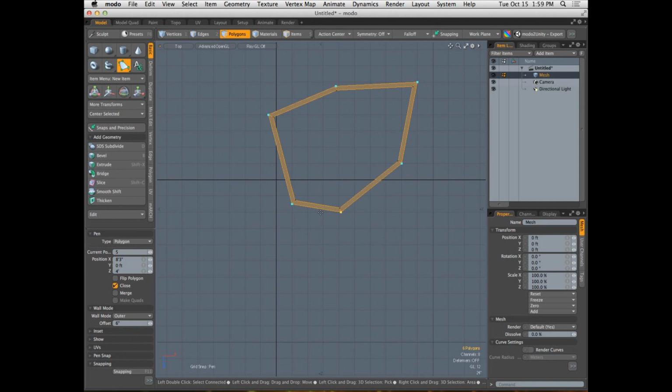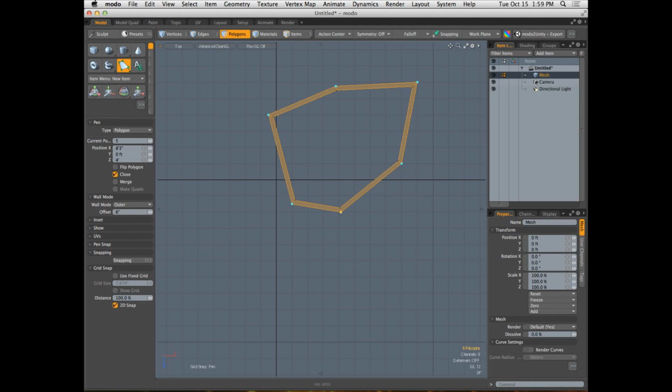The snapping engine allows us to activate some really cool functions inside the pen tool because I'm still not getting those perfect 90-degree corners that I'm after. Check it out. It's pretty neat. I want you to continue to look at some of the additional pen tool options right below, and specifically where I'm going here is pen snap. Inside of pen snap, we have 3 different options, and right now I've deactivated the snapping system, and you can see that they're grayed out. These 3 options are turned off because the snapping engine is not on.